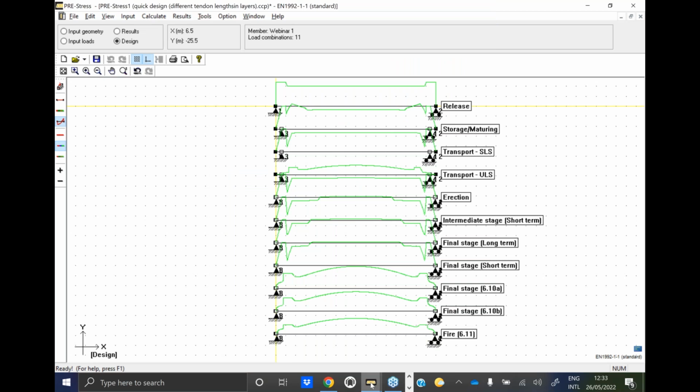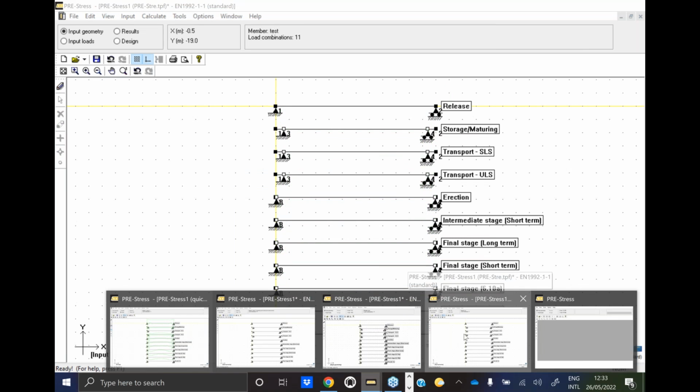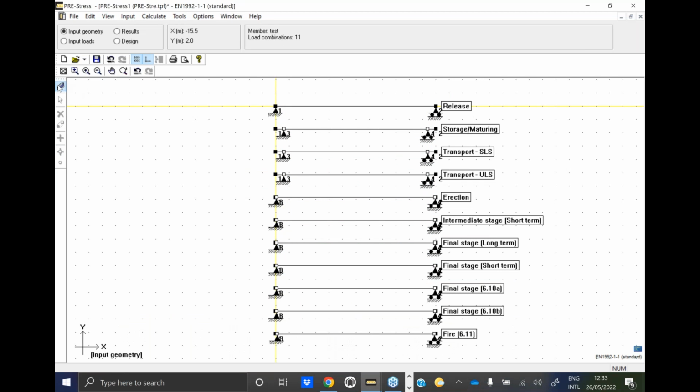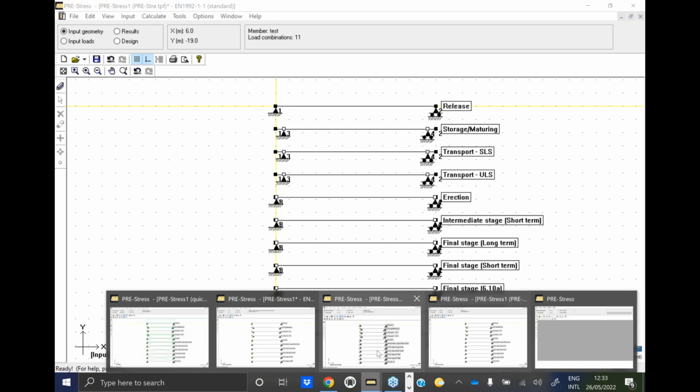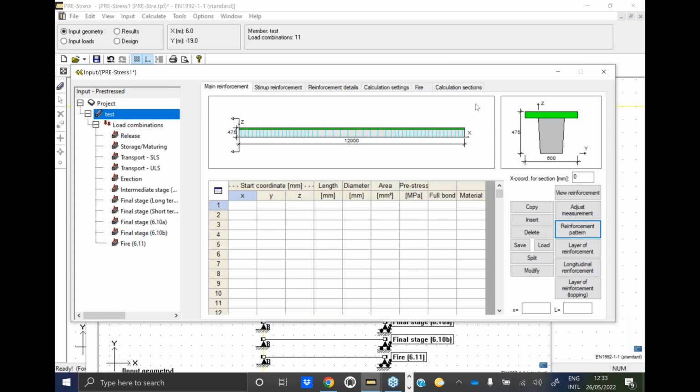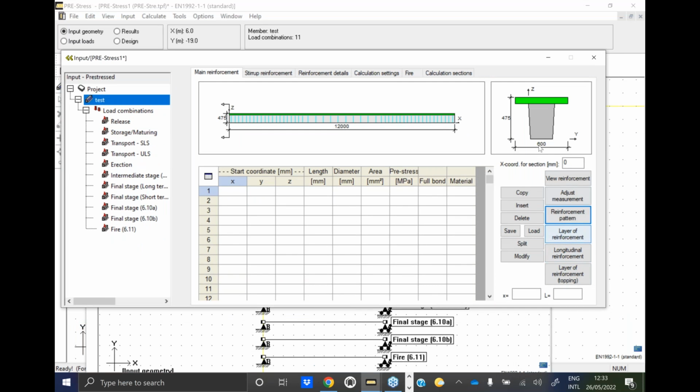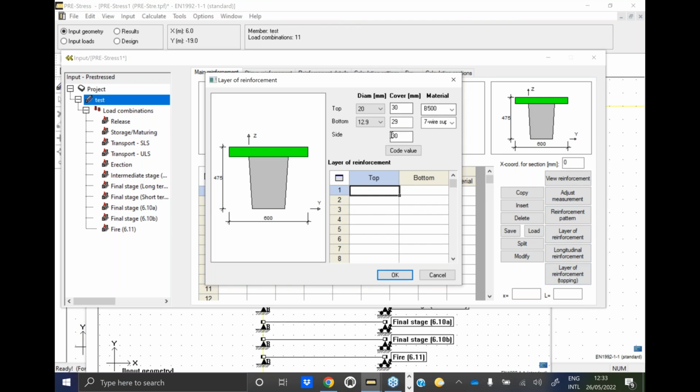Now, what I forgot to mention in the model we have created together, I hope this is the one. Let's see. This is the one. All right. I can also place reinforcement inside the topping. So I can do top. I will just do one layer of reinforcement, for example 6, and it will place 6 bars in longitudinal direction in this cross section.